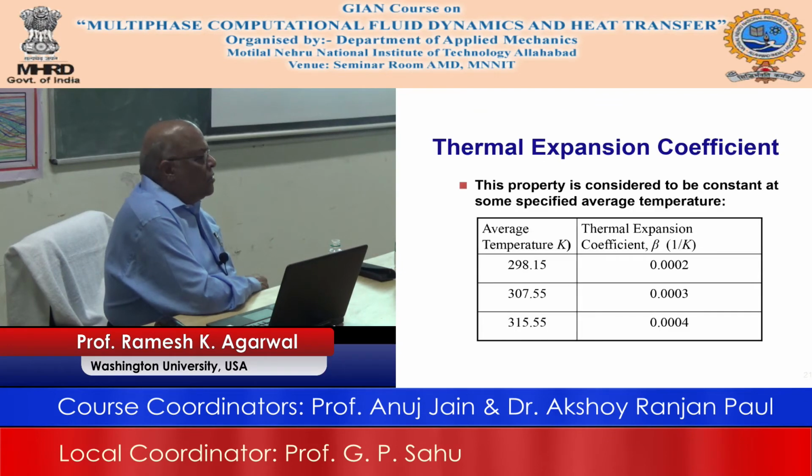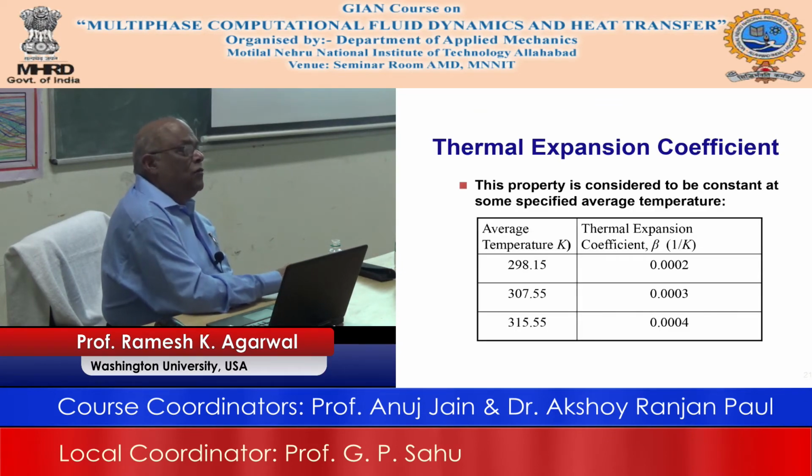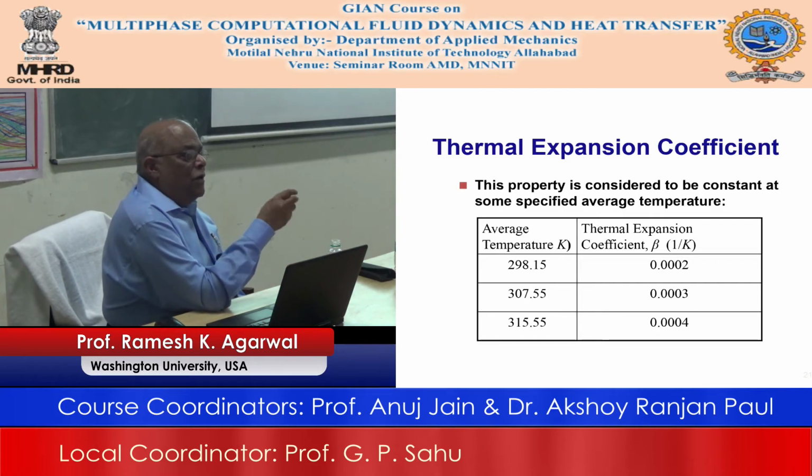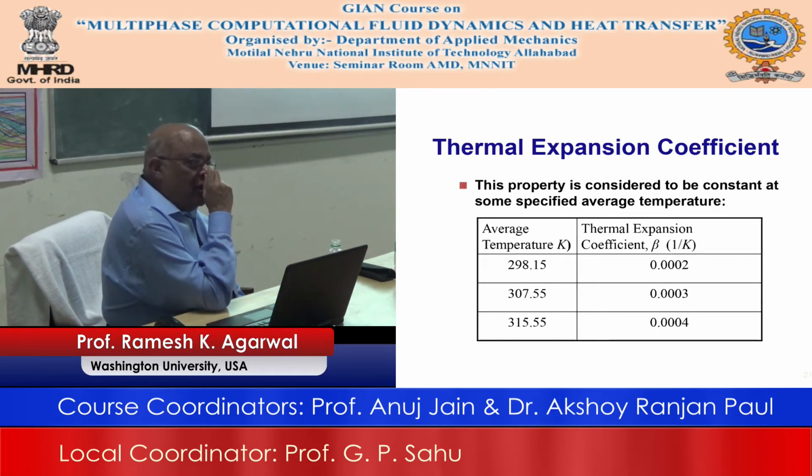All right. So if you look at all these properties that you are needed, you can just put them in Fluent in 1 second, right? I mean, you don't even need to write a UDF actually. You can directly substitute these numbers in. But if you want to add these formulas, you can write a simple UDF and plug them in. All right. So, a very, very simple multi-phase flow of particles plus the fluid, but you are treating it as a completely single phase flow without any other addition at all. And then you are solving a new problem by treating it as single phase, but you have to be aware of what the assumptions are.